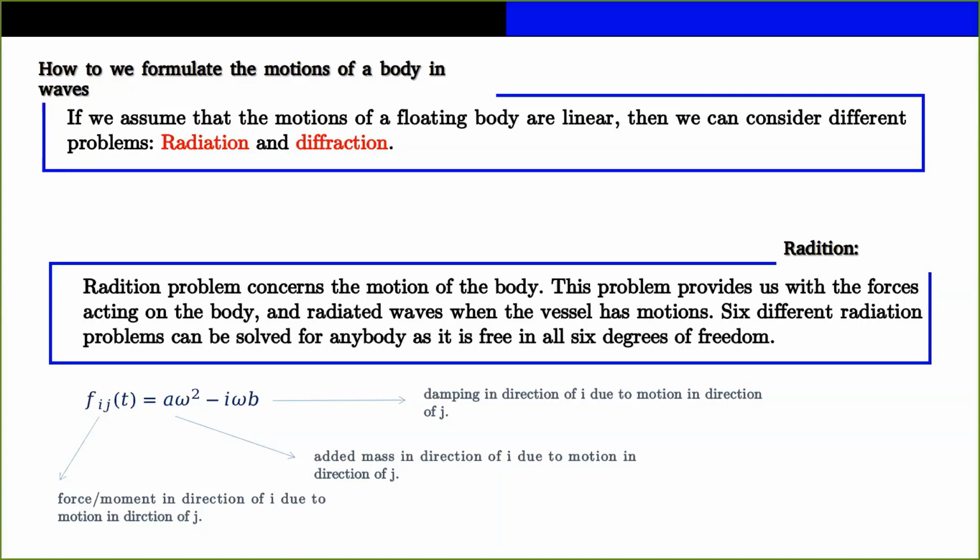You can see that the word itself is talking about the problem: radiation. It's like radiation of waves from a body. Radiation itself just concerns the motion of a floating body, and it doesn't have anything to do with the water waves. But it tells us how a floating body, when it's moving and oscillating on the water surface, can generate waves, and in response to its motion, fluid can generate some forces on it.